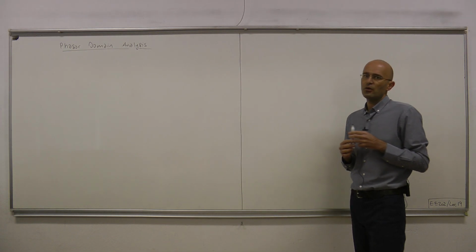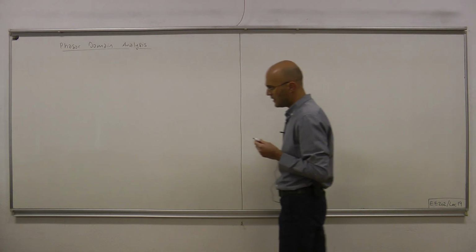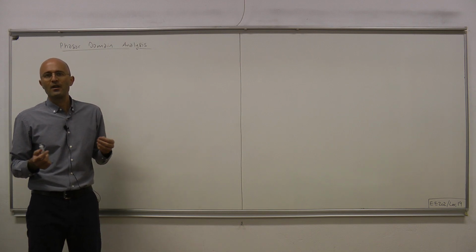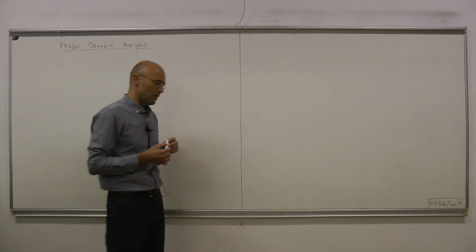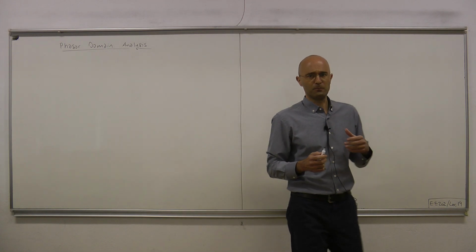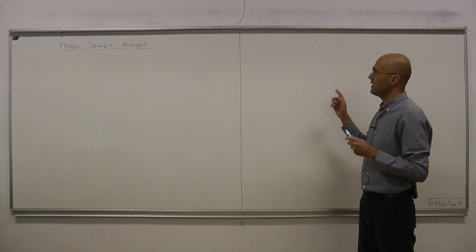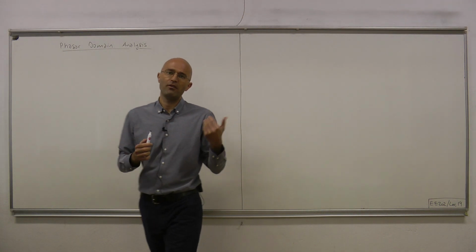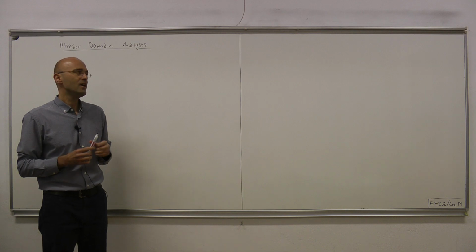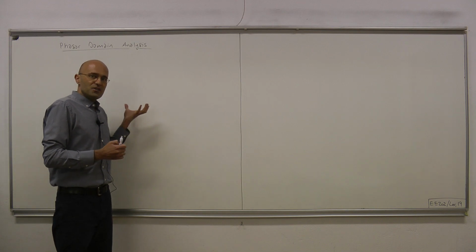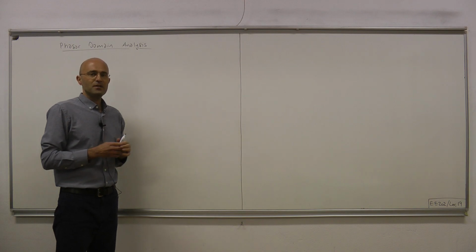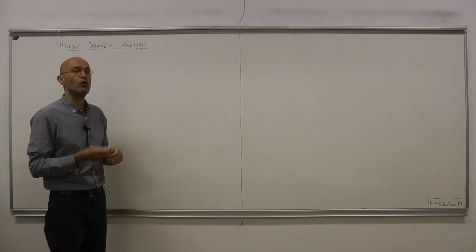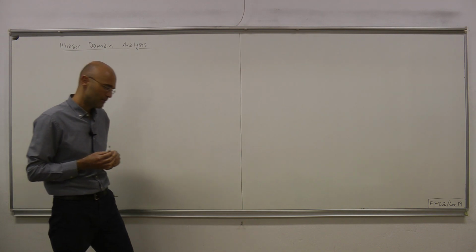For such a circuit, we realize that each signal can be represented by a complex number, where the magnitude of that complex number would be the amplitude of the sinusoidal signal, and the phase of that complex number would be the phase of that sinusoidal signal. So a time domain signal, a sinusoidal signal, can be represented, which was a very simple observation, by a complex number, or a vector on the complex plane, if you will.